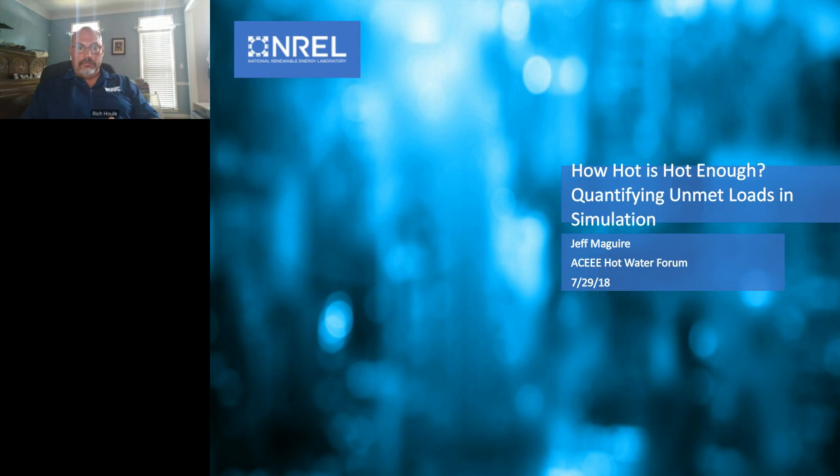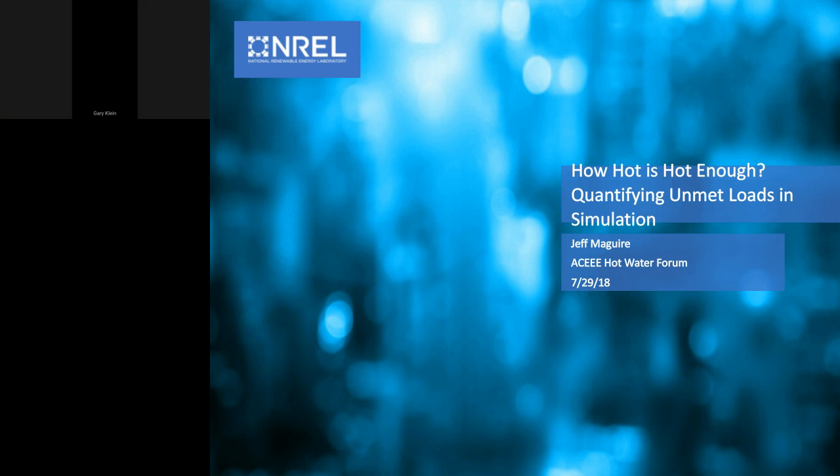Thank you, Rich. One of the things that we found in our research is that the pressure drop per fitting actually goes down as fitting sizes get bigger, particularly for insert fittings. It's true for all of them, but the particular interest is the insert fittings. Because they're sort of the same wall thickness of a fitting, but the diameter of the pipe is twice as big, so it takes up less of the middle. And so that's not what all the handbooks talk about right now. The pressure drop per fitting gets bigger as you go up in size, and that's just not what we're measuring at all in the lab. So there's still some interesting confusion that needs to be sorted out, which is why you and I have this conversation all the time about what needs to get measured next.